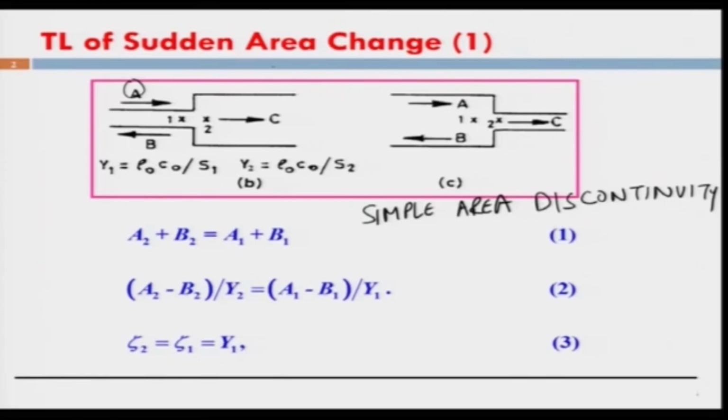If you consider a simple expansion chamber like this, what this figure does is break it into a sudden area expansion, where the area change is positive or the area has increased, and a contraction, where the area is suddenly reduced. The idea is to have an impedance mismatch at these ports, so that most of the acoustic power, or a significant amount of it, is reflected back. Let us see how it works and how things are related.